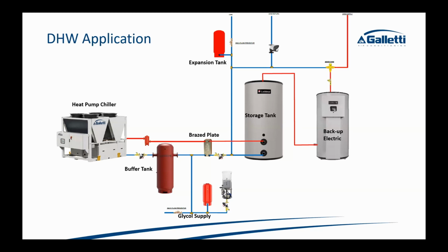So some technologies out there are other heat pump options. We see a lot of promotions sometimes for CO2 units. Now, what a CO2 unit would require is a single pass. So let me talk a little bit about this unit. A traditional unit puts hot water in, pulls cold water out, and takes multiple passes, probably increasing 5, 10, or 20 degrees, depending on the temperature and the flow rate. But ultimately, it's passing multiple times before it gets that storage tank up to temperature.